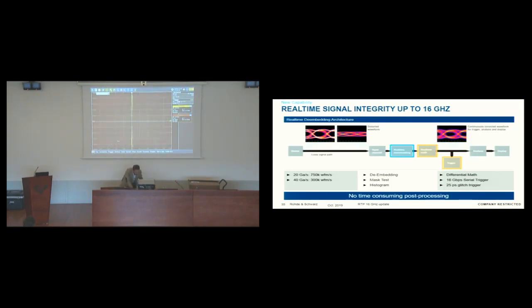Okay. So as you can see, this is the signal. Channel 1 is the positive polarity, and channel 3 negative polarity. Of course they are inverted, so that's why we are triggering here on a positive edge, and here we have the negative edge in the negative channel. Of course they are inverted.